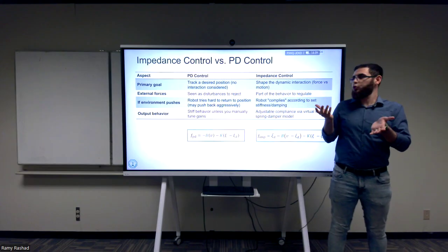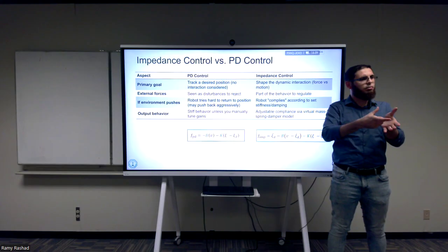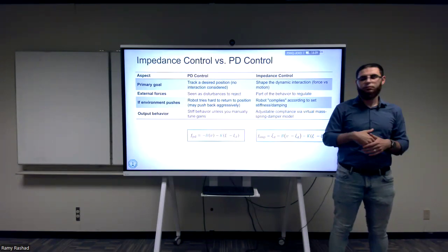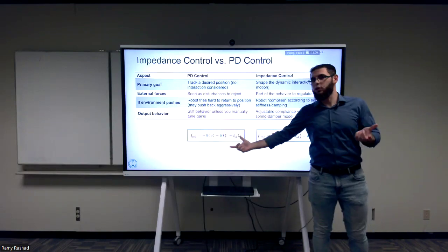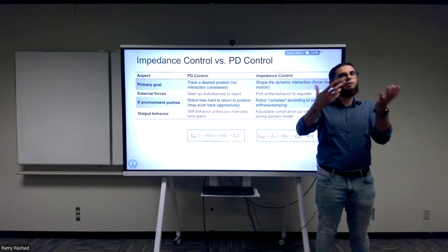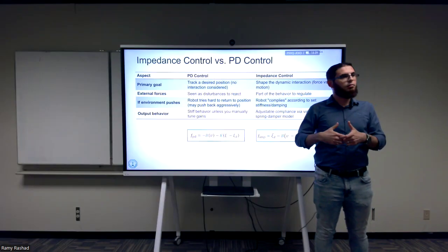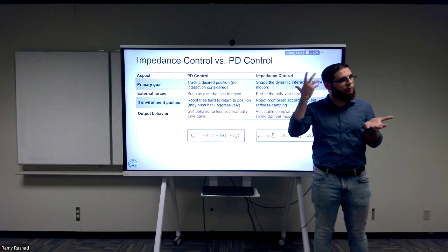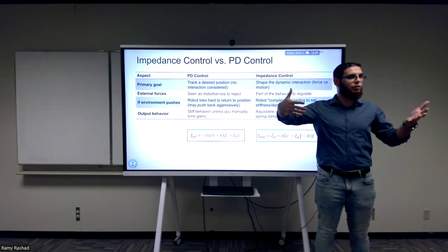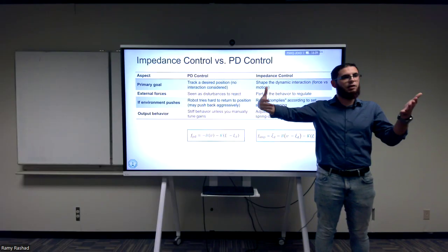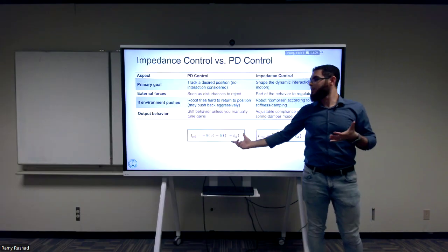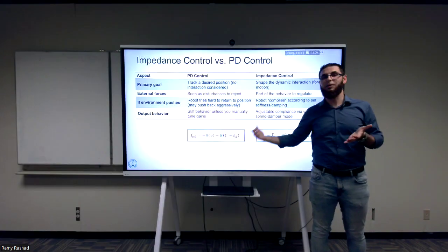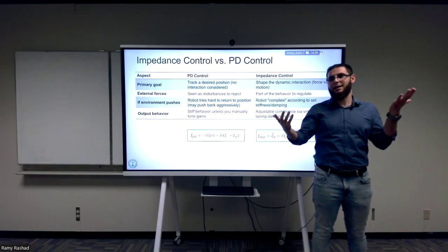When we were designing the PD controller, we thought about the error, multiplied by some gain, took the error dot, and we got the controller. This was the same controller that we got when we thought about a potential function. We took the gradient of it, and we took the damping injection. It was the same controller, but we got it from a different way of thinking, looking at the shaping of the energy, balancing of the energy. When we thought about PD control, we were not able to extend it to the geometric setting on SO3 and SE3.